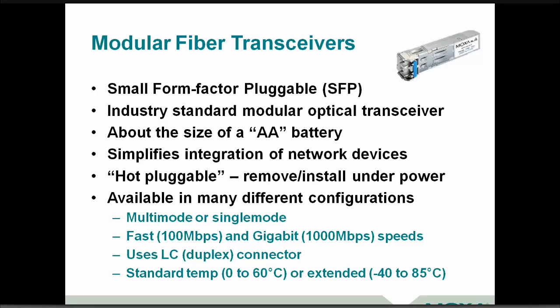So this little SFP module that we're looking at up here, always being remote, it's hard for you folks to get a gauge of size. If I were to lay an AA battery side by side, it's about the same size, or maybe the size of your small finger. The electrical connections on the right-hand side plug into your media converter or switch. And here are your fiber connections that accept the LC connector over here on the left.